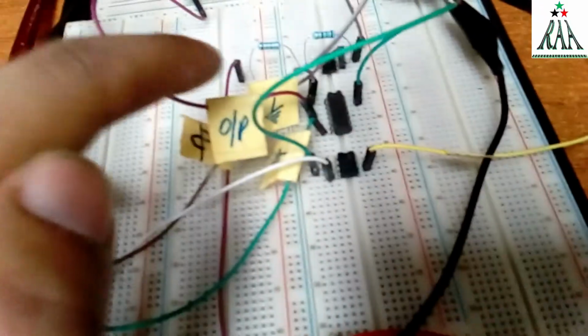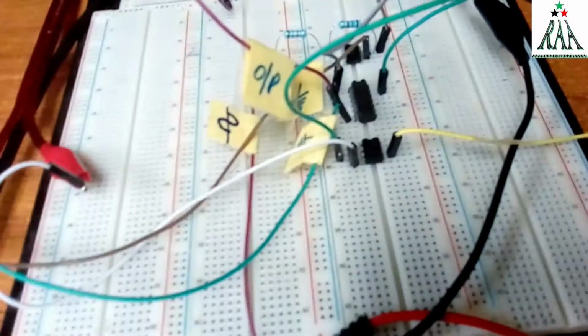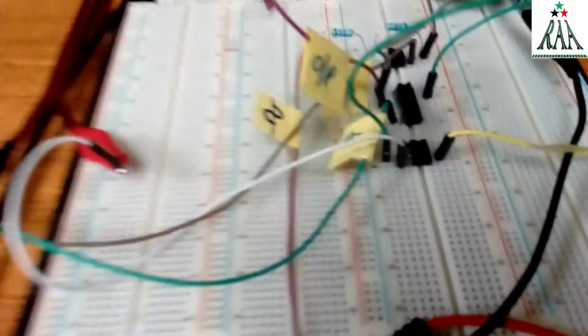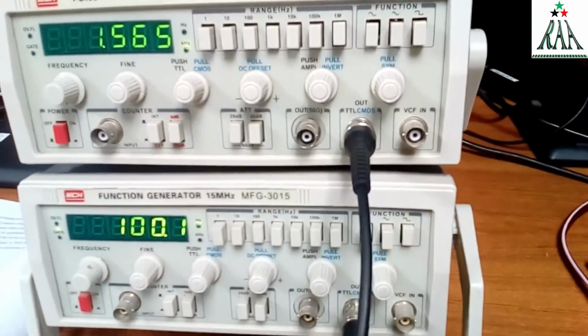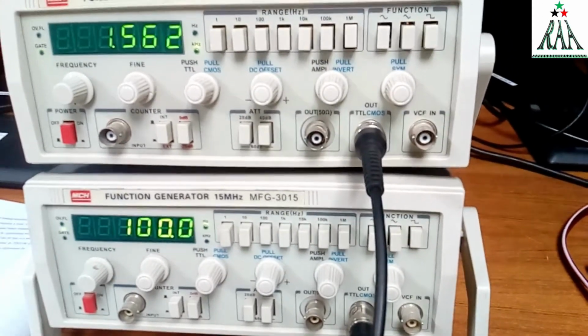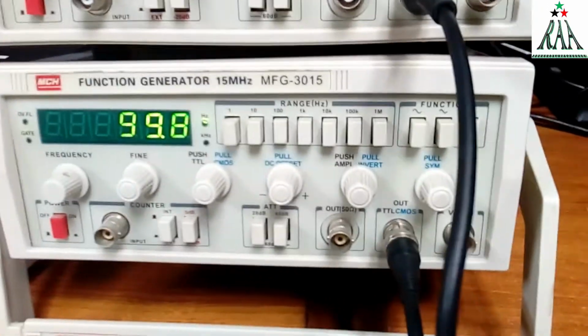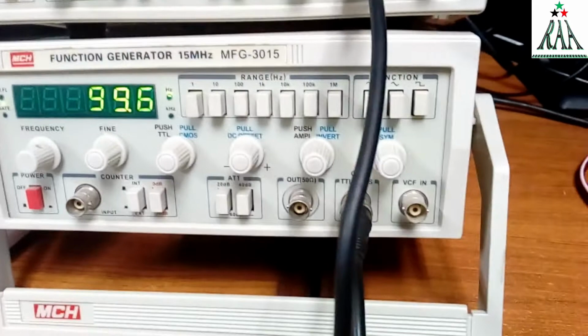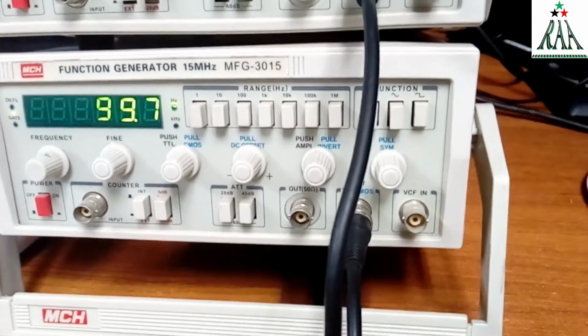We are taking our output from this port, and we use two op amps, and two signal generators have been used. One gives us the 1 kilohertz sine wave, the other is the TTL digital signal with a frequency of almost 100 hertz,